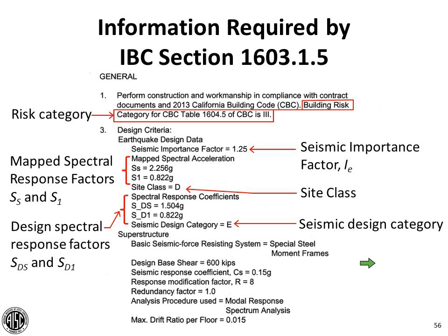Well, seismic design category A has no seismic requirement, and so no, you wouldn't have to show it. In seismic design category B, it says that the seismic parameters are supposed to be shown even if seismic design does not govern. They have a similar requirement for showing the basic wind speeds, for example.